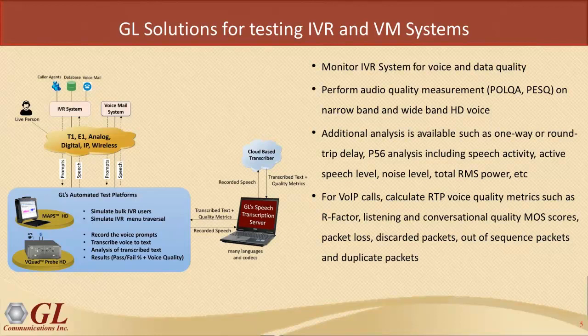We can perform P.56 analysis, including speech activity, active speech level, noise level, total RMS power, and so on. And for voice over IP calls, we can calculate RTP voice quality metrics such as R factor, listening and conversational quality MOS scores, and provide additional packet information such as packet loss, packets discarded, out-of-sequence packets, or duplicate packets.